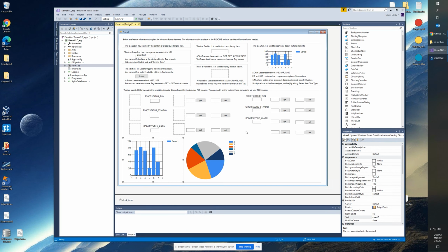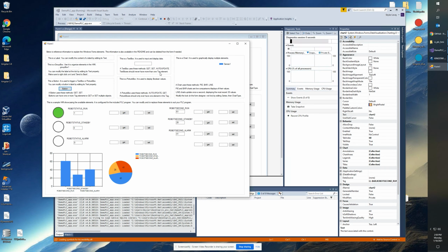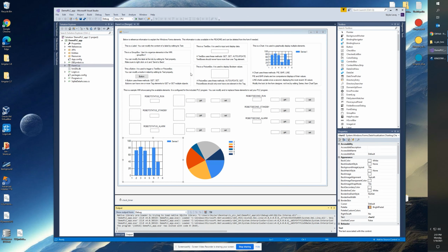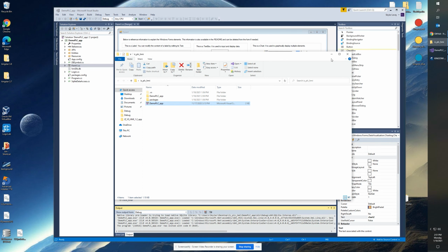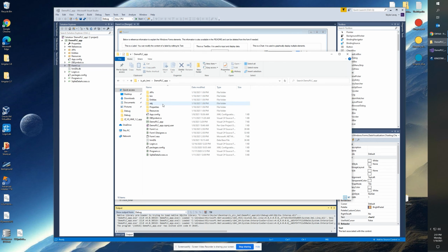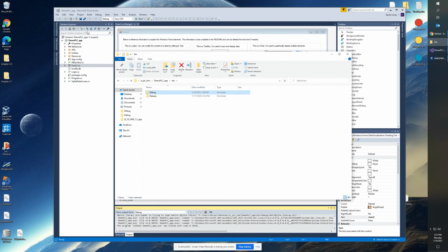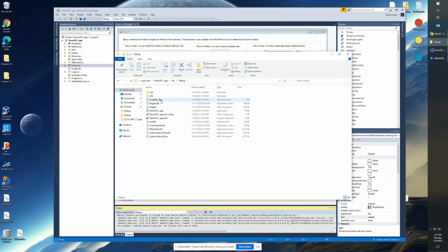One of the features of the HMI is that, on every startup, all available data bindings found in the provided PLC sample application are written to a text file named available tags. To generate this text file, we will start and then immediately stop the project. To access the file, go to the root directory and then click on the project folder, then binaries, then debug because we just ran it in debug, and then finally available tags.